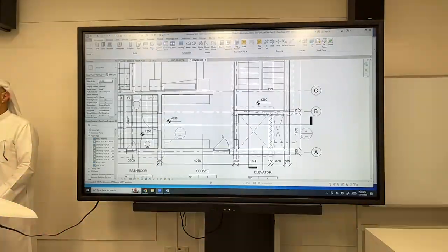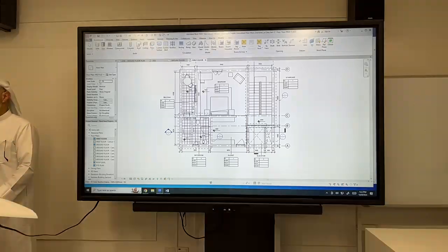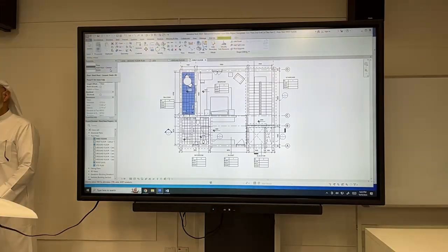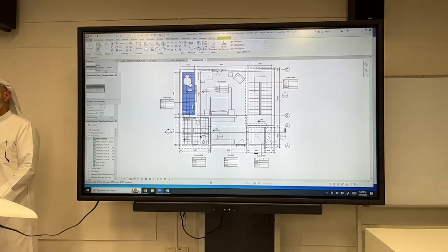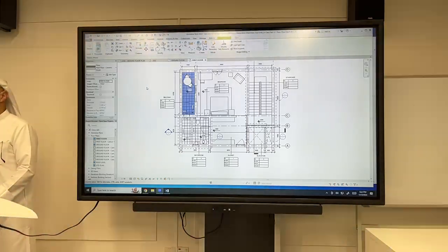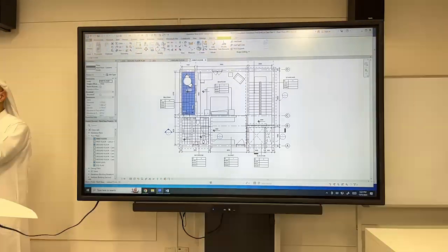Any questions about floors? For the balcony, what's the floor type? It's a roof. Okay. It's a ceramic finish. You should at least change just the size. Actually, for the roof, it's fine. If you have time, which you probably won't, just leave the roof as is. But make sure that it's selected as roof floor.